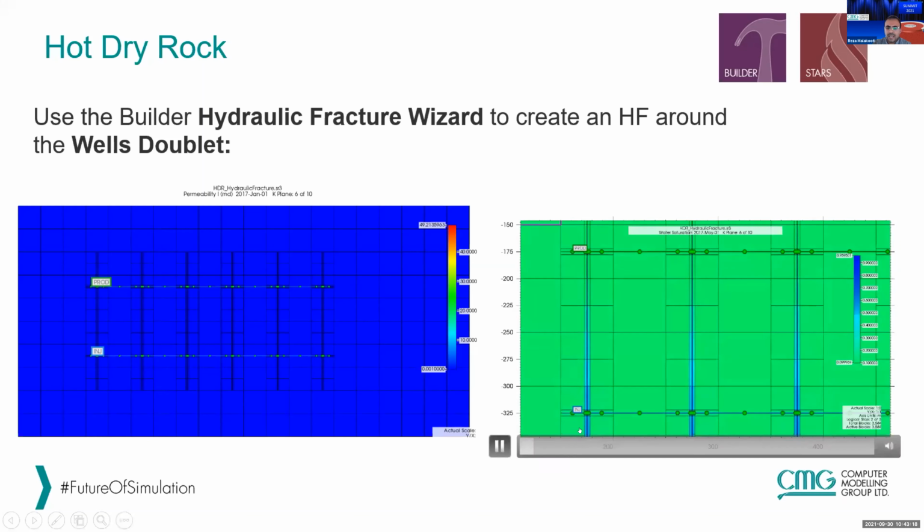In that example, you can see that we have modeled the required completion in that single well by using concentric tubing to capture the concept of injecting very cold fluid into the bottom of the reservoir, and then producing back through the tubing that hot fluid from the bottom hole.